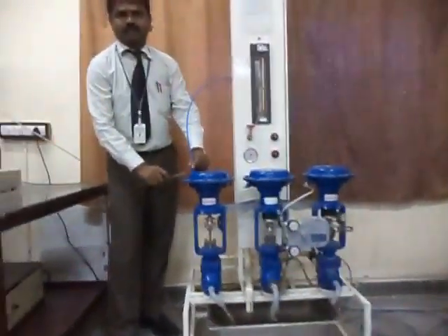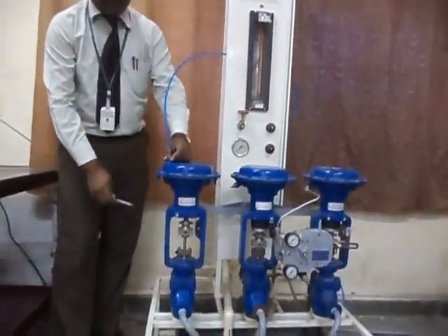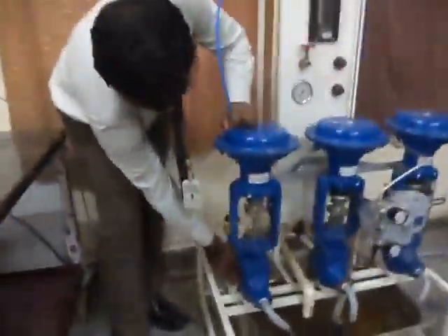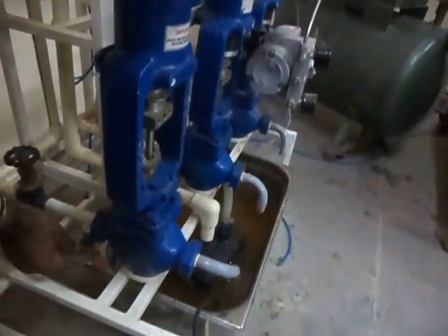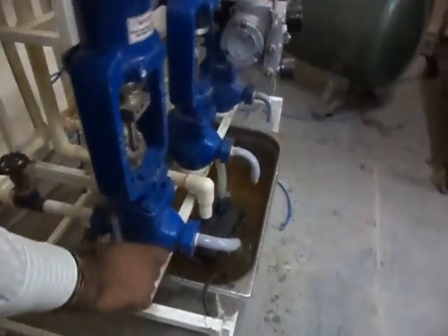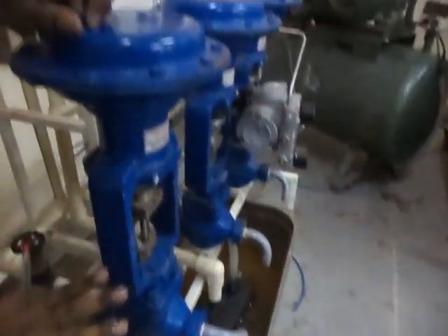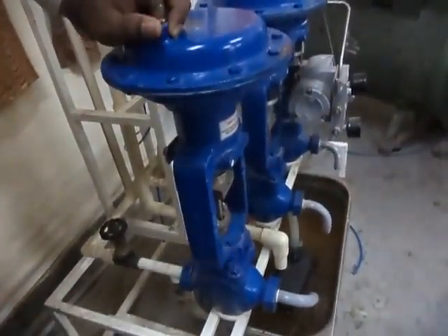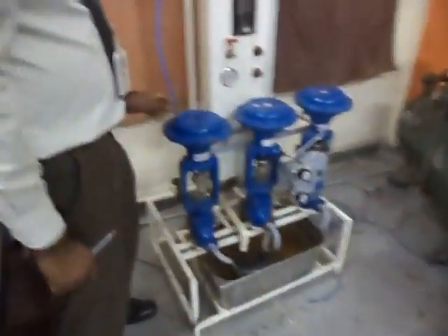Actually the control valve setup has the control valve connected in the pipeline, but we have to close this pressure coming across this control valve. So this is closed here. So the control valve exhibits its characteristics purely based on the control valve alone, and the pressure across this pipeline will not affect this control valve's characteristics. So the setup is arranged for inherent characteristics.